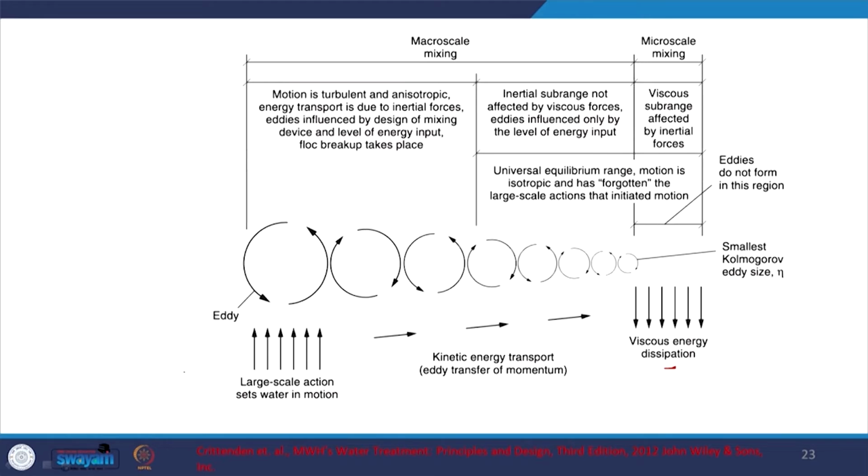So, here I am going to start my motor. Large scale action sets water in motion from my impellers or fans in the water. So, I am going to form eddies, and these eddies lead to transport of the energy from one eddy to the other into smaller and smaller eddies, let us see.